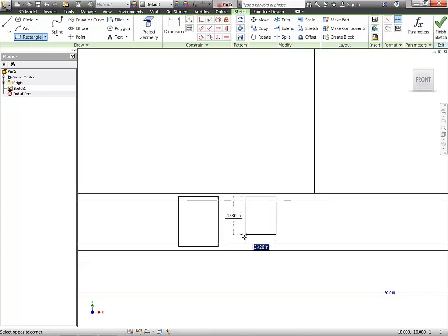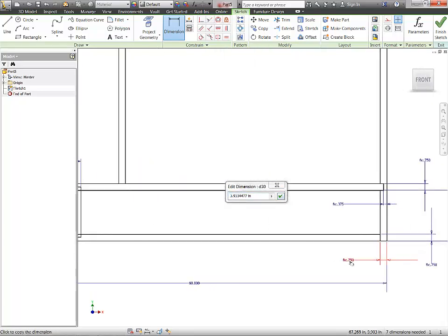I'm now doing some of the dividers at the bottom piece. Just draw in a sketch. It doesn't have to be exactly correct. Add a couple of constraints. These are collinear constraints, and say it's 3/4 of an inch. Okay, and make it equal the original.